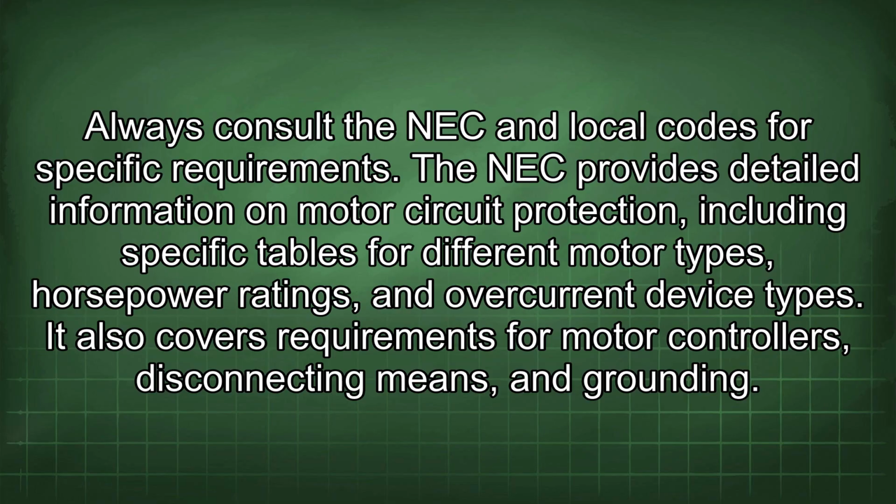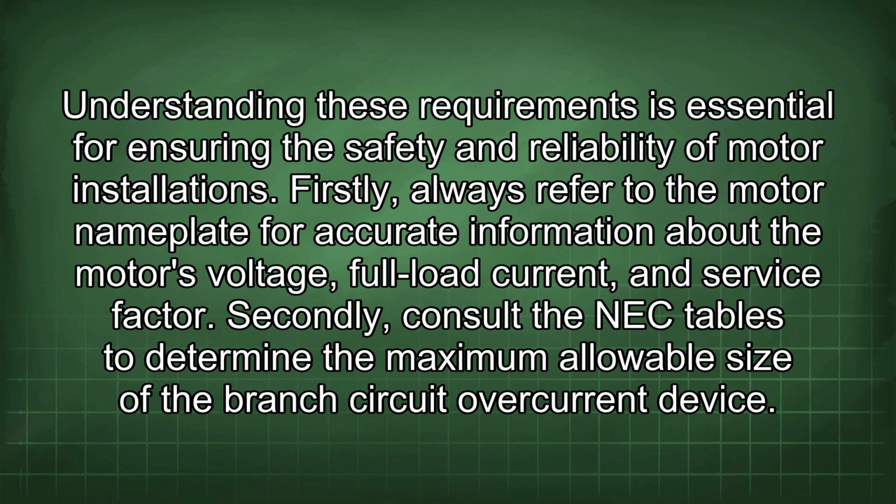The NEC provides detailed information on motor circuit protection, including specific tables for different motor types, horsepower ratings, and overcurrent device types. It also covers requirements for motor controllers, disconnecting means, and grounding. Understanding these requirements is essential for ensuring the safety and reliability of motor installations. Firstly, always refer to the motor nameplate for accurate information about the motor's voltage, full load current, and service factor.